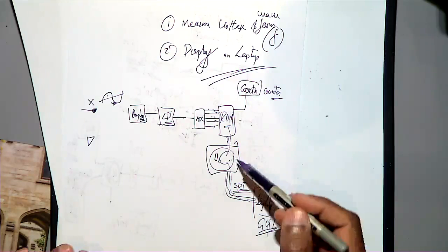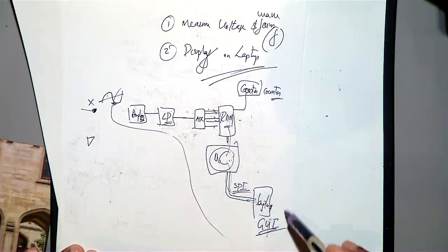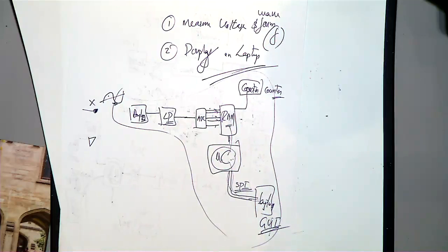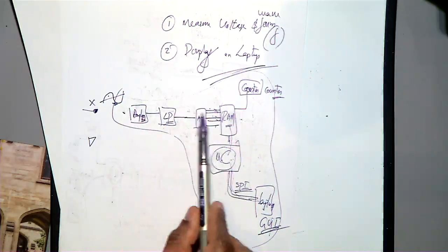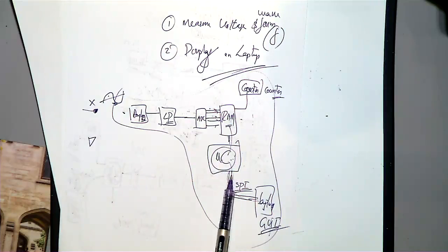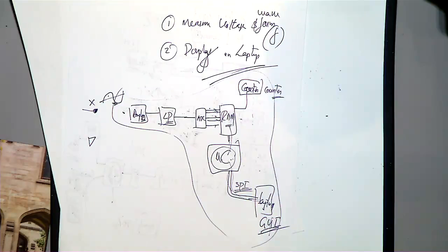So this is a kind of a code representation of DSO. And then here you are just displaying using the microcontroller, then you are displaying in the laptop. But now we will be thinking in the oscilloscope, you are getting some waveform that is converted into digital form, and then digital form you are storing in the RAM, because you need in the system a RAM for putting the data. So whenever you design a system, if you want to read it to the PC, you need a RAM, so that you are writing in the RAM, then later you can read from the RAM.